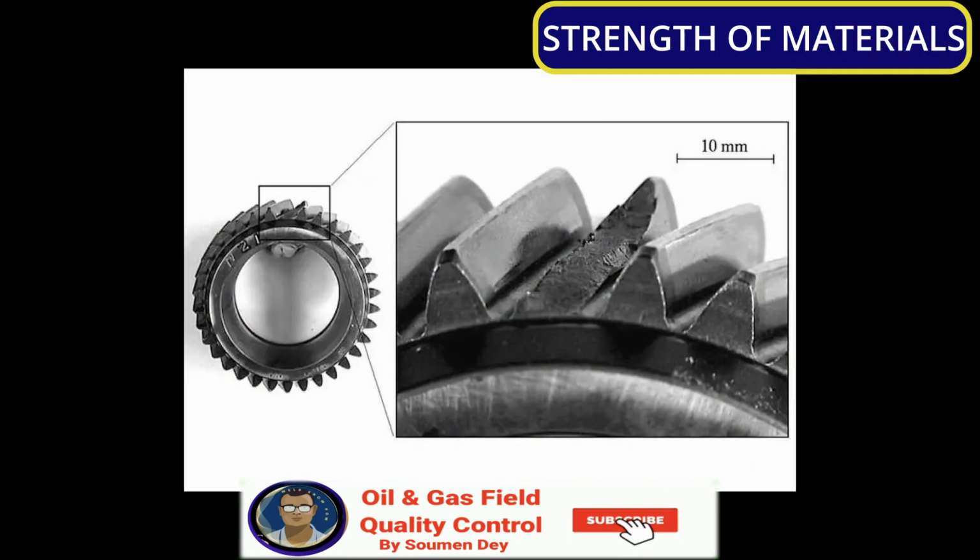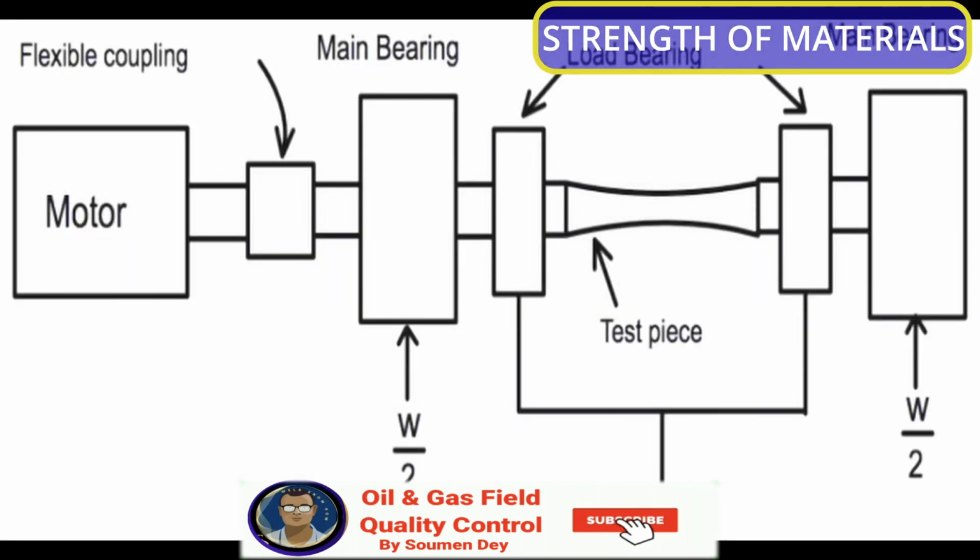Fatigue strength. Fatigue strength is the maximum load a material can withstand without failure during a large number of reversals of load. So this is called cyclic or repetitive load. For example, a rotating shaft which supports a weight has tensile forces on the top portion of the shaft and compressive forces on the bottom. As a shaft is rotated, there is a repeated cyclic change in the tensile and compressive stress. Fatigue strength values are used in the design of aircraft wings and other structures subject to rapidly fluctuating load. Fatigue strength is influenced by microstructure, surface condition, corrosive environment, and cold work.